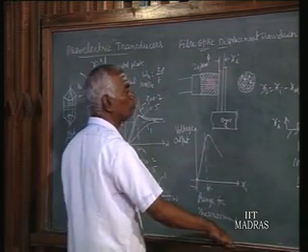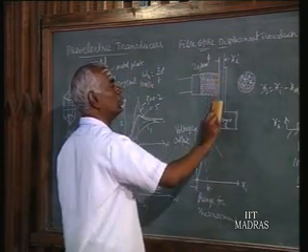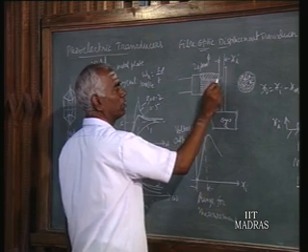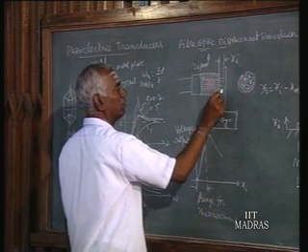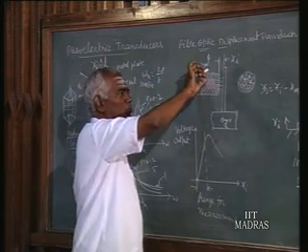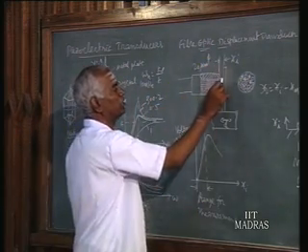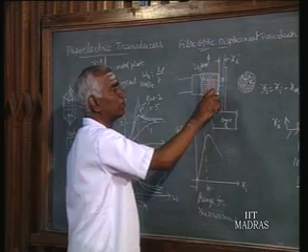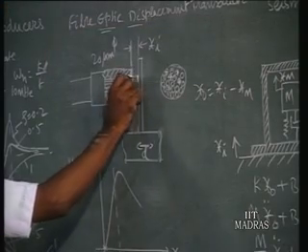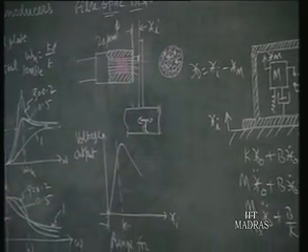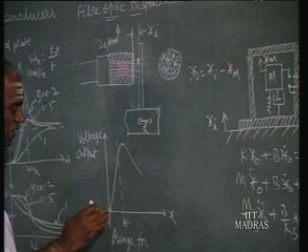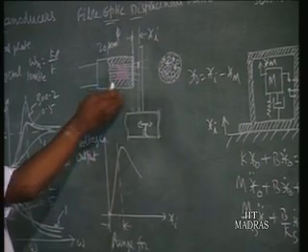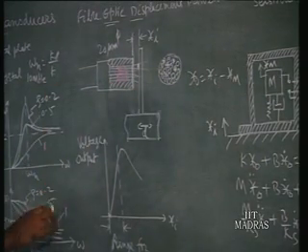Now as this moves away from this point, the light carrying fibers, we find the light beam travels in a little conical fashion, and depending upon the distance, this is the area of reflection. The area of reflection depends upon the distance from this tip end. The more distance means bigger area, because the light will be dispersing like this. So depending upon the area, reflected light also increases. So as xi increases from 0, reflected light increases, and hence the pickup fiber picks up more light and that goes to the photodetector, and more light comes, more voltage will be produced.